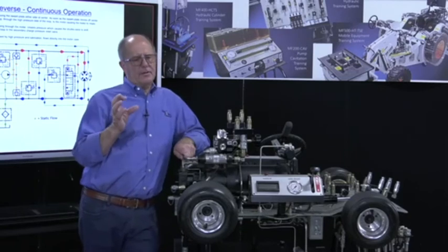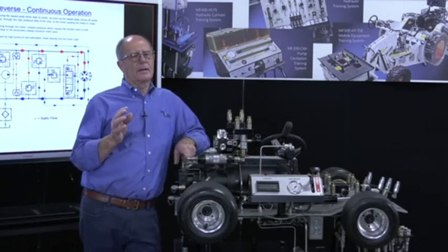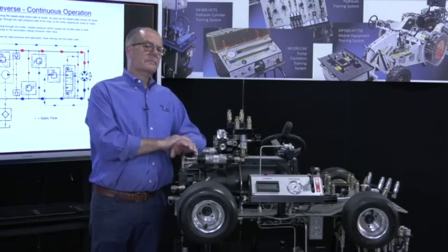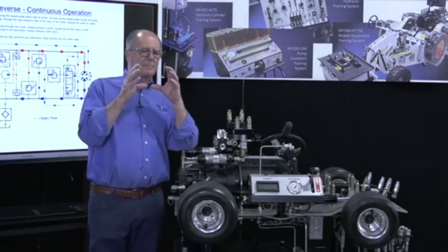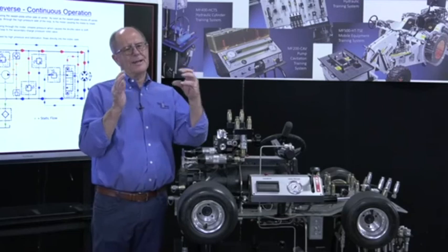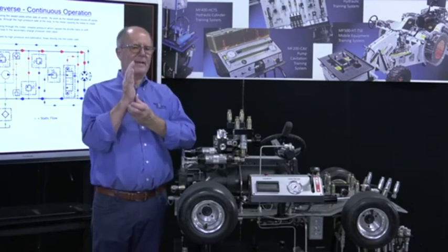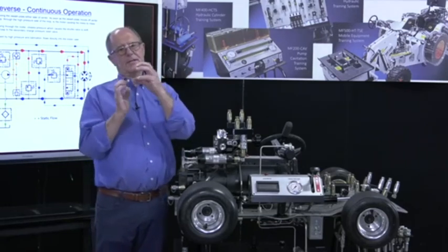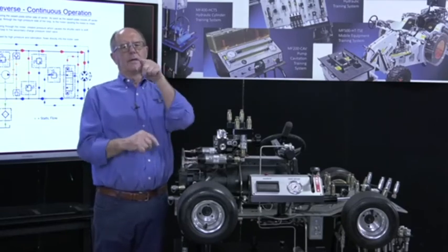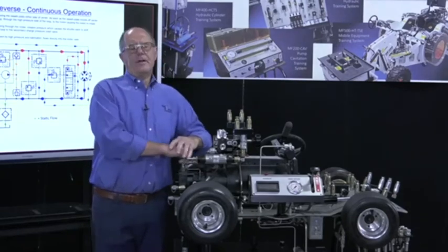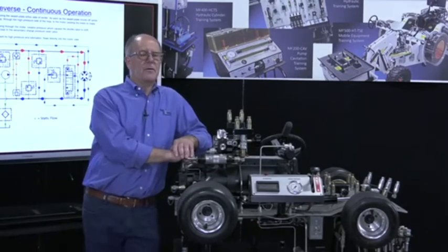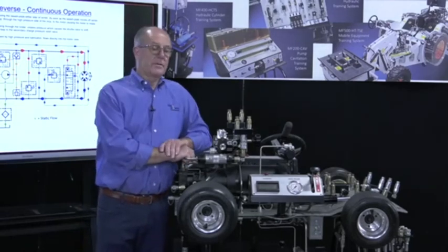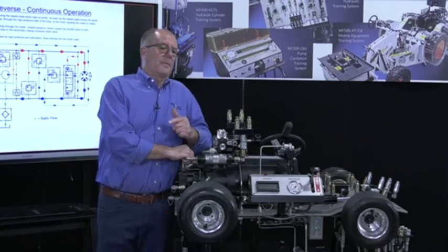Now, the reason why you want to do it in reverse is because if you've got any kind of fitting like manufacturers will make for hydrostatic drives, they'll make a T, an elbow. But they may make it out of a piece of steel, so they drill into the steel from one side, and then they'll drill in the other side. But when you drill in, it's going to leave, where the two holes come together, little wells in there. Now, every fitting is a centrifugal filter. So if I've got oil coming at high velocity around a corner and it throws the dirt into the corners, it's not going to come out unless I go backwards. So the prudent thing to do is to go in reverse.